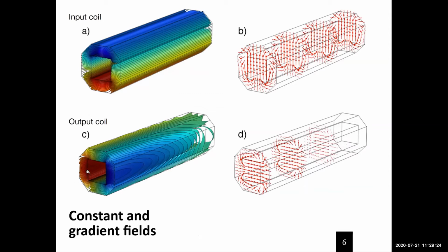You can see that the winding density is higher at the beginning of the coil, and then is less dense at the exit of the coil. So this produces the tapered magnetic field that we need for that component. So it's a strong transverse magnetic field, and then it decreases along the length of the spin flipper. And we have something similar, perpendicular, for the other component.